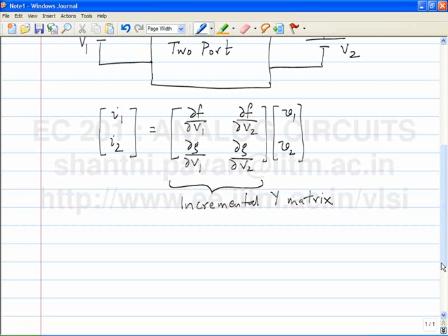And we saw last time that we all accept that as long as the error is, say, 1% of the approximate value, we still qualify that as a small signal. So by the same token, earlier in the one port case we had a one-dimensional Taylor series. Now we have a two-dimensional Taylor series, and the higher order terms, if the sum of all those terms is, say, a small fraction of the first term, we assume that it is small signal